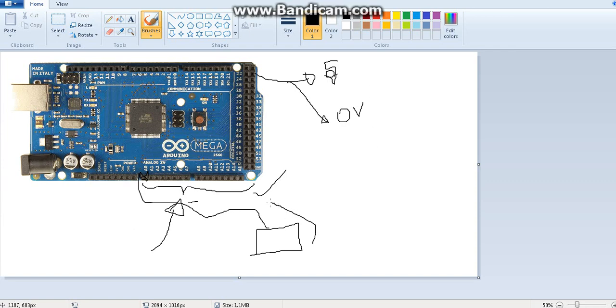Likewise, if you are giving an input, you are basically giving a voltage. Remember, normally any sensor or input source that works under 0 to 5 volts is used with Arduino. So that device can give a voltage between 0 and 5 volts as an analog input, right? Again, take this digital output. This pin can give either 0 or 5. It cannot give intermediate values. Can it give 2 volts? No, because it is digital, 5 or 0.